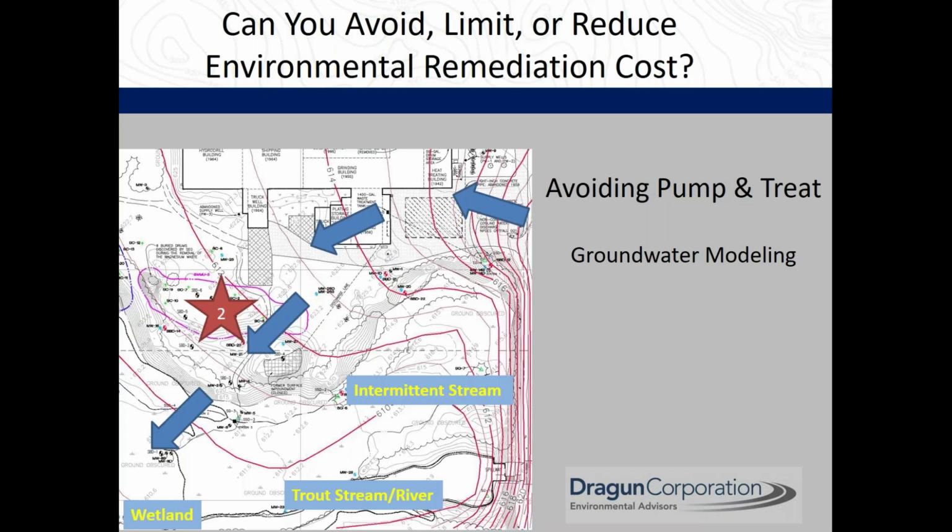And you'll notice in this particular slide, there's some very steep groundwater contours along the right side of the slide. And just so you don't think we had contouring gone wild like Mike talked about, those were due to where this river starts at the bottom of the slide. It's dammed up at the roadway, and there's a large lake to the right of this slide that causes that steep groundwater. But as the groundwater flows away from that influence, we see that it flows much more along a southwesterly path.